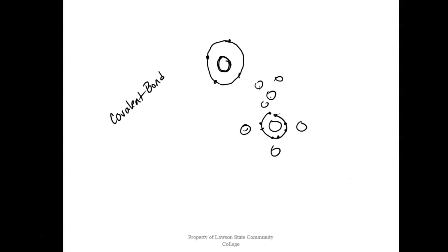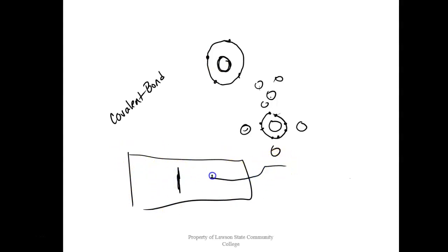And then we take elements and combine them with other things to make compounds. So what we do is we deliberately come up here and through diffusion, we'll take the silicon and they'll put it in a big nice tube. And then they flow gas through it. It's either going to be a pentavalent, which means what? It has 5 in the valence shell. Or they use a trivalent, which has 3.